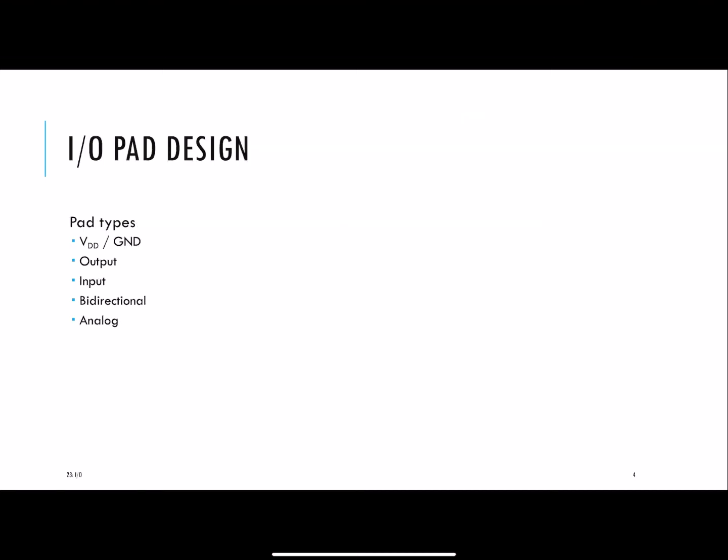Okay, so there are different types of pads. What the I/O looks like, let's say, is a buffer driving a large piece of metal, and you wire bond to that piece of metal. I'm really simplifying the drawing here, because this piece of metal has a stack of layers underneath it, etc., to make sure you don't cause any mechanical problems. But the idea is that this might be a landing pad, might be 75 to 100 microns per side. Strictly speaking, that's called the pad. But people like me call this whole structure a pad.